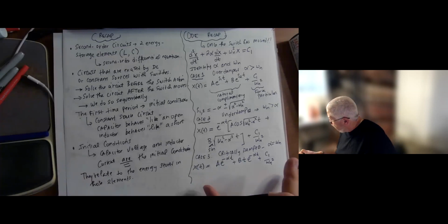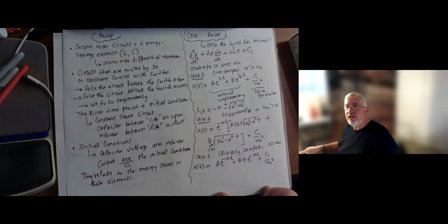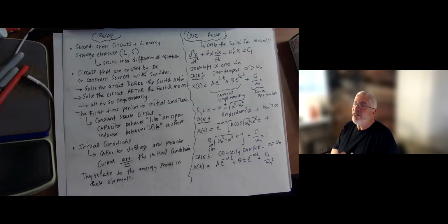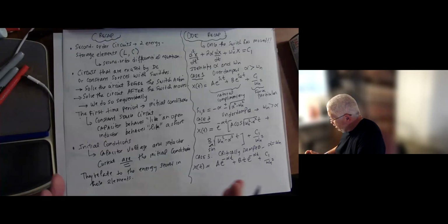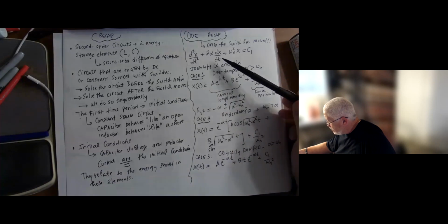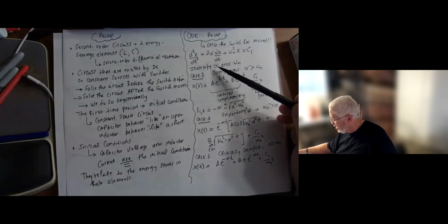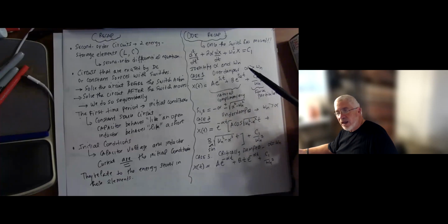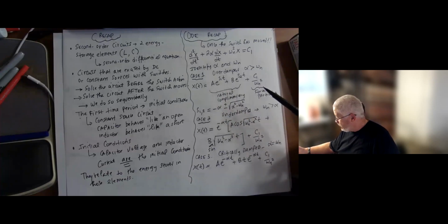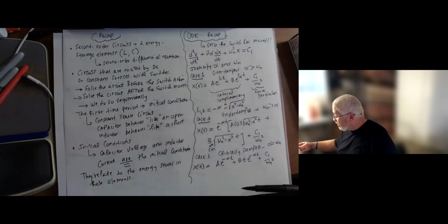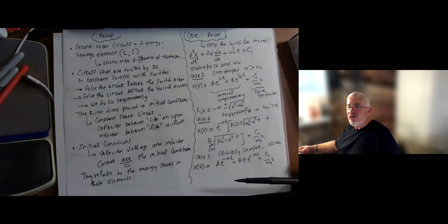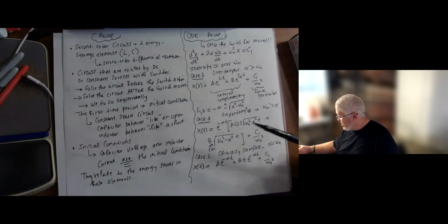This is a good summary of your second-order differential equation content that pertains to Engineering 17, the circuit analysis course. These are things your differential equations course looked at very early, so it's not something complicated. Again, no need to prove any of that. Once you get the differential equation via nodal or mesh analysis, I need you to identify alpha, identify omega n, tell me which case we're dealing with, and write the general solution. Then the remaining step is to use the initial conditions to calculate the constants A and B in each case.